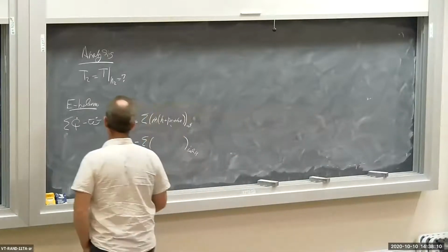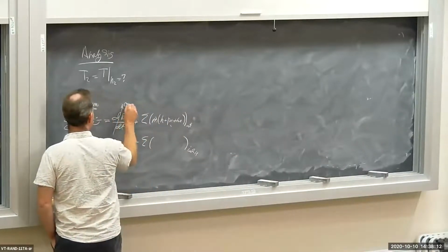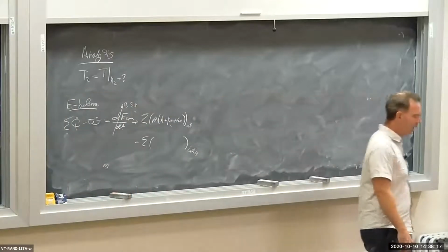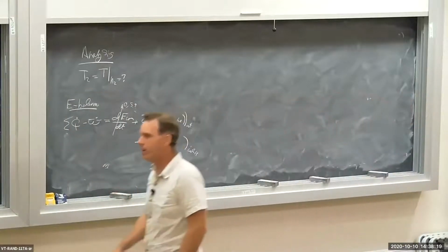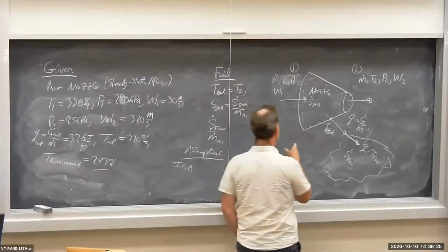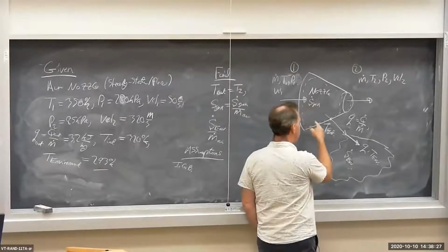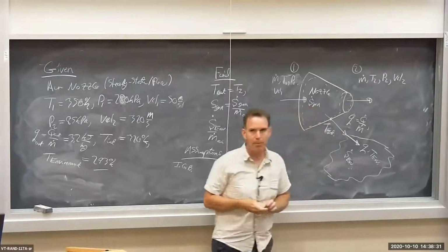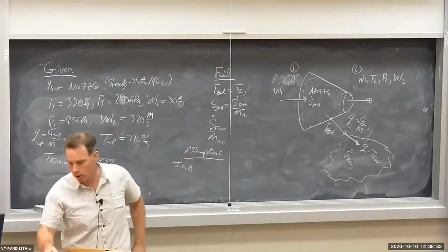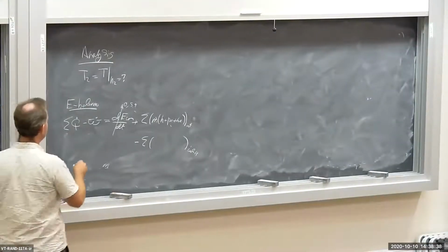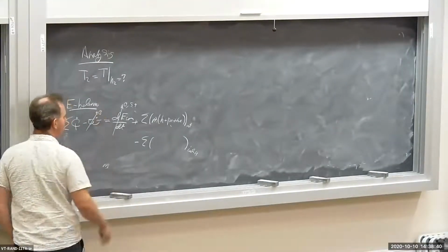Now it's a steady state problem, so this is zero. Steady state, we're given the steady state nozzle. I don't see any non-pressure work going on here. I don't see any wires. I don't see a propeller in here. I don't see that the nozzle itself is deforming in terms of shape and size, so there's no boundary work going on. So I can immediately get rid of this work term here. So that's gone.